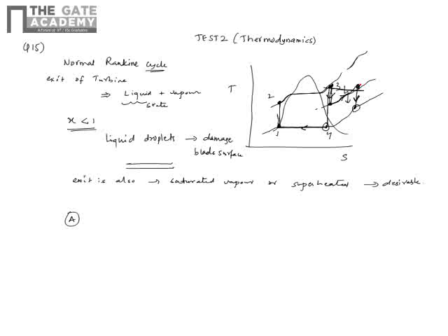Well, it increases in fact, because the condenser now has to reject more heat. This is the entry point of the condenser. It has to lose more heat, so that is also not the option. Reduce fuel consumption? No, it increases fuel consumption, because you need to supply some fuel to heat in this part. So B, C, D are not the option.